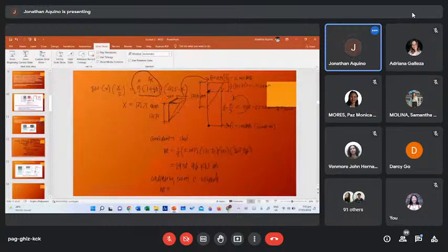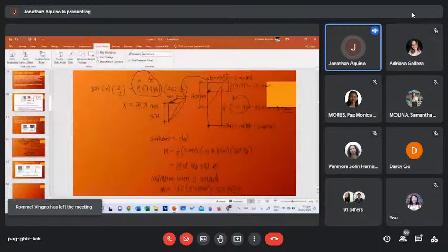So, 140 times 9 times 1940 millimeters squared times the lever arm. The lever arm, either take a moment on the steel or take a moment about the centroid of the concrete, is just simply d minus x over 3, or 367.76. So the moment capacity is equal to 140 times 9 times 1940 millimeters squared times 367.76 millimeter.